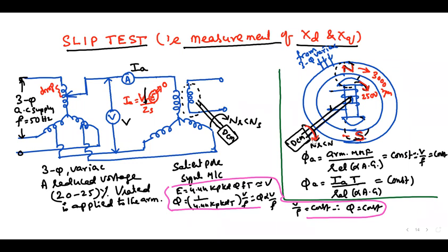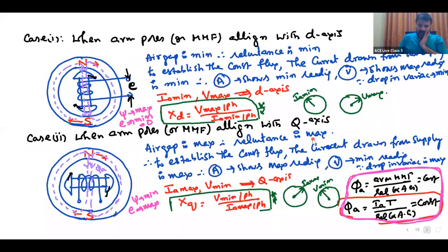Here, when you are calculating line voltage, say for example, examiner gives slip test results. Voltmeter reading line to line is 400, star connected. Then what is the XD? You have to take it divided by √3 and current per phase. Anyhow, in star connection, line current and phase current are the same. If phase values are given directly in the slip test results, V phase maximum is this, V phase minimum is this, current phase directly given, then you can take XD directly, no conversions are required.